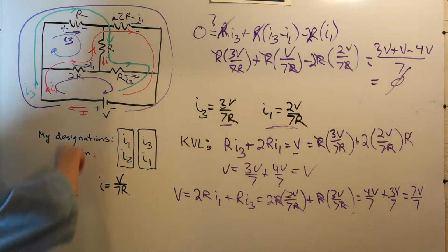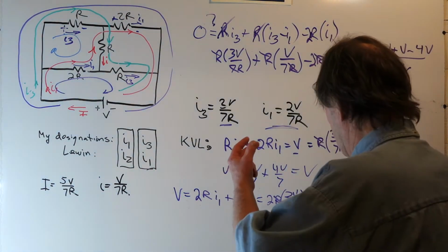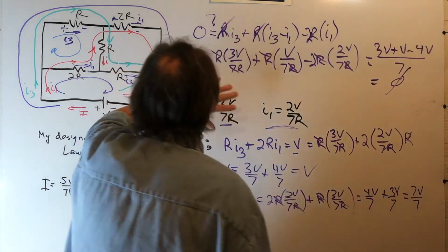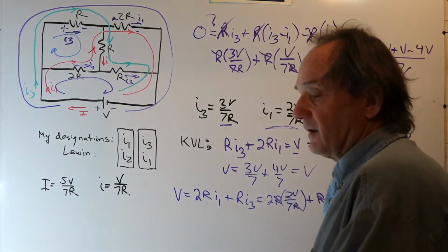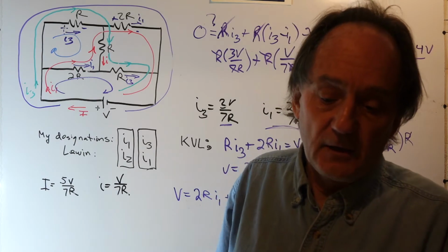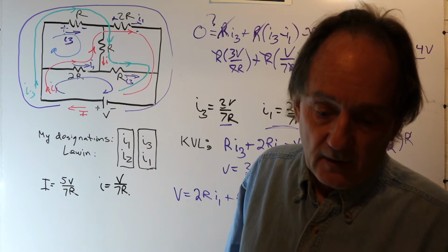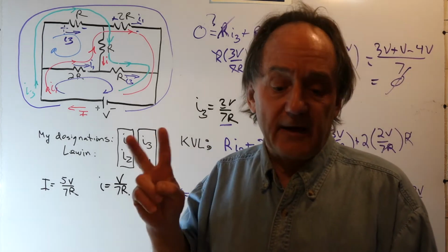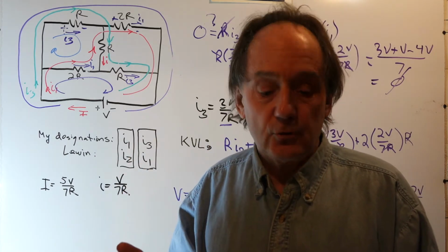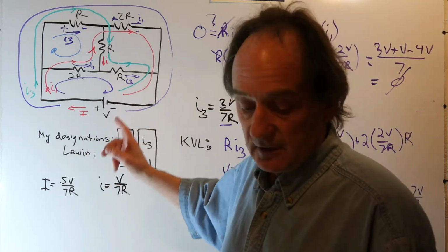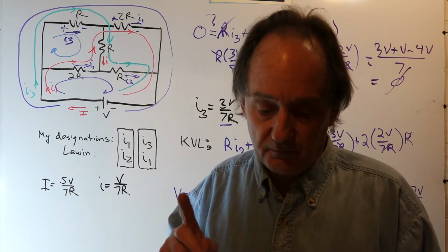This is a solution using the two-loop current method. Kirchhoff's voltage laws are satisfied in other loops than the ones we used to calculate it. So this is the solution. Uniqueness guarantees it. Now, what about the case when this upper right resistor is changed to 5R? Can you use the same two-loop technique? You most certainly can. It does not matter how you choose and assign the arbitrary currents in the loops as long as all of the circuit elements are touched and included by the currents.